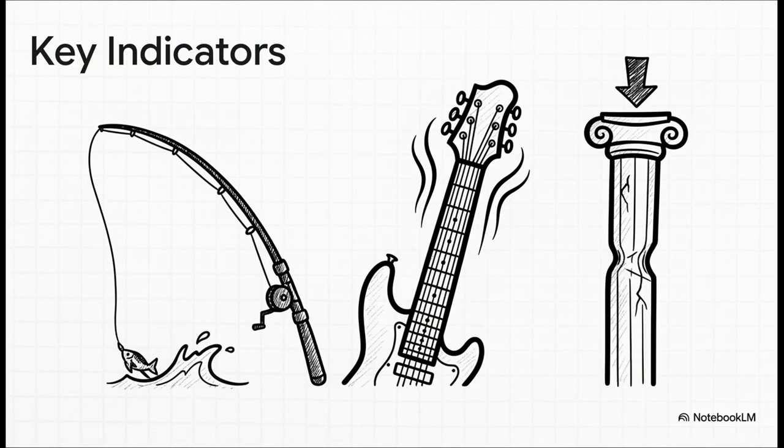So when should the alarm bells for geometric nonlinearity start ringing in your head? Anytime you're dealing with something long and skinny or thin and flexible. We're talking about a fishing rod bending way over, a cable on a bridge swaying in the wind, or that thin metal column that's about to buckle. These are all poster children for cases where the changing shape is the main character of the story.